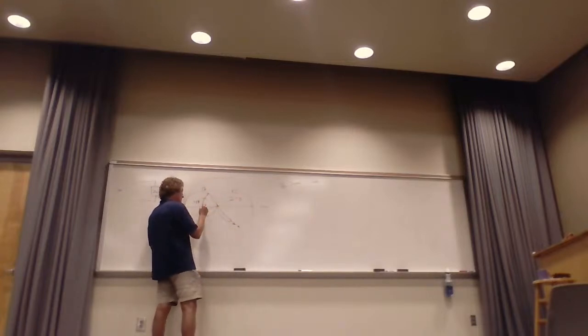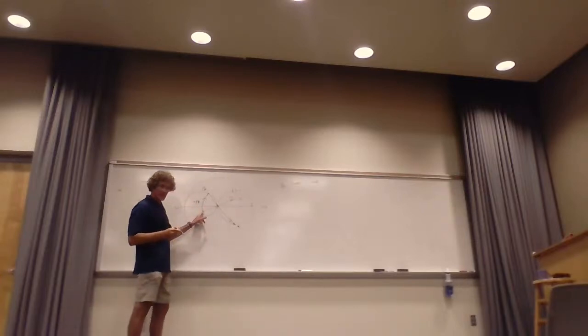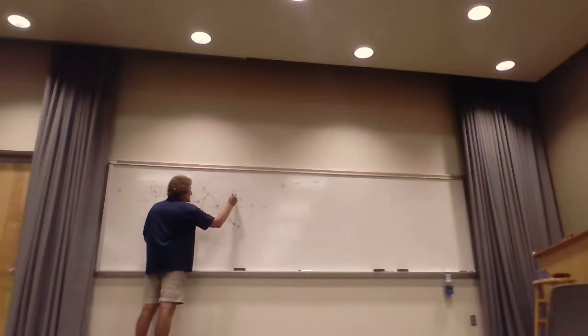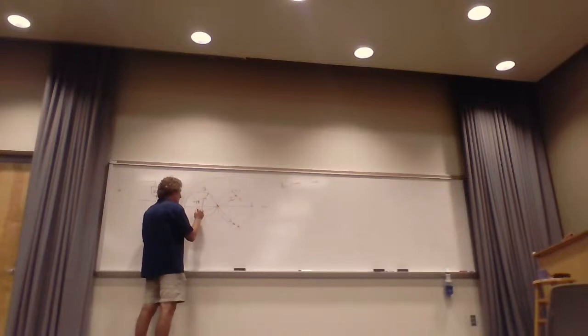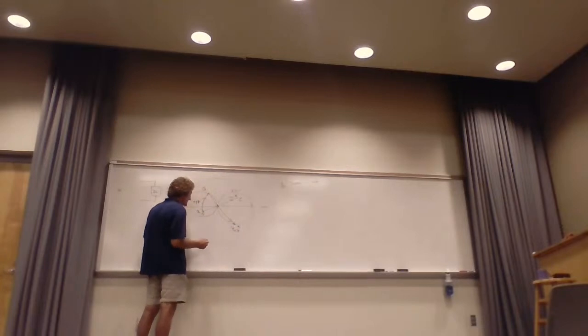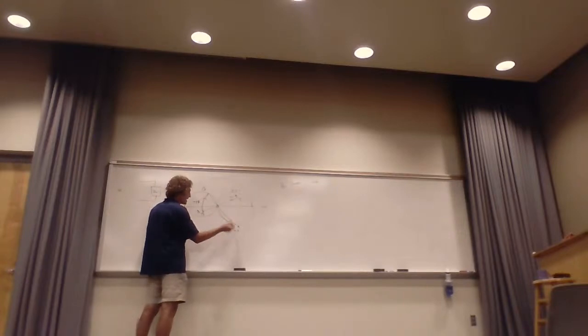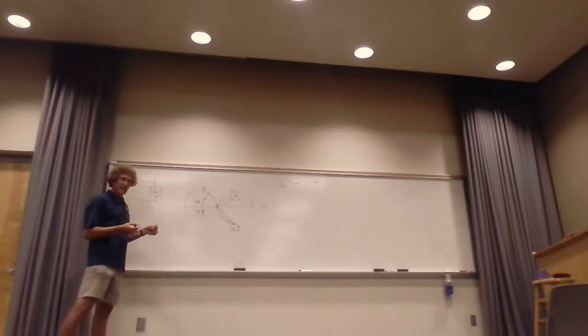Well, here I came in, took 1 over that. I didn't really move. I'm just now looking at the admittance, right? This is ZL. This is YL. Then I get rid of the imaginary part. Now I'm here. Then I go from the admittance domain to the impedance domain. I have 1 plus jx, I'll just call it x here. It doesn't matter. And now what I'm going to do is add a minus jx to get back.